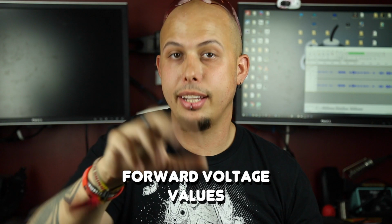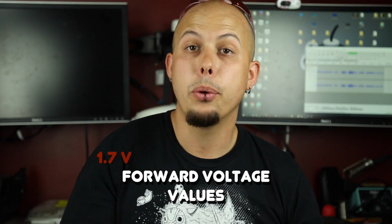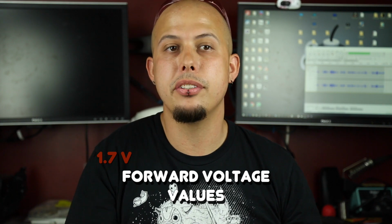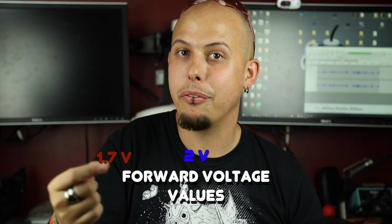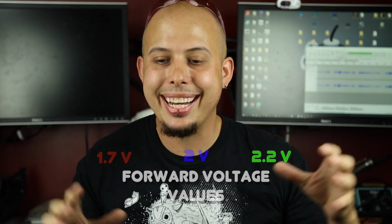For example, my red LEDs here have a forward voltage of 1.7 volts, whereas my blue LEDs have a forward voltage of 2, and my green have a forward voltage of 2.2. I can have each of those in the same 5-volt circuit, but since they have different forward voltages, I will choose a different resistor value for them to have the same intensity or the same current going through those LEDs.